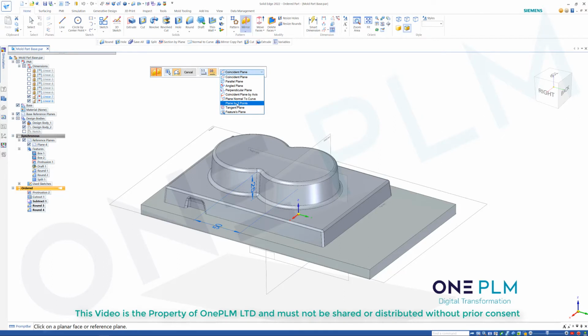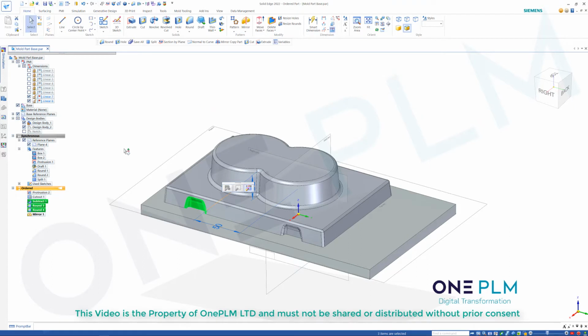For this we want to choose plane normal to curve, so this allows me to produce a plane at the midpoint of that edge. So if I put 0.5 in the position, that's going to produce that to there, and then finish. And then Control and select the mirror, and then do that again, and we're going to go and do that over to the other side.